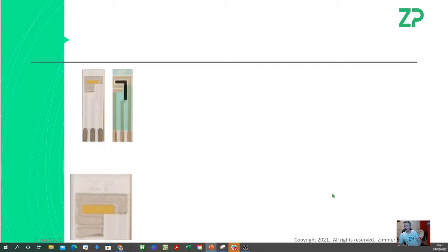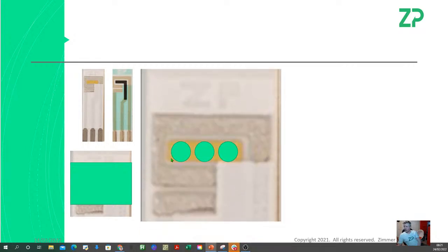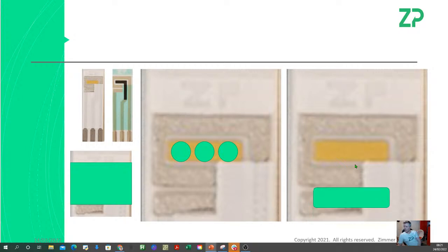How you actually functionalize the electrodes is this. You take the working electrode, which is the central part here. This one is a gold one. You don't flood it like that. Flooding will just put everything everywhere. We actually just put 3 1 microliter drops along here, and they often merge to give you 1 drop here.